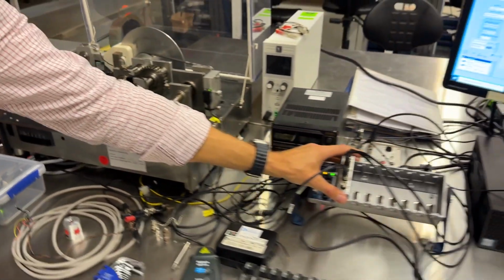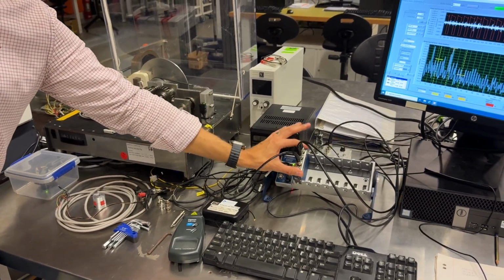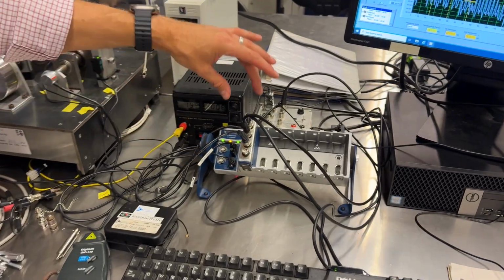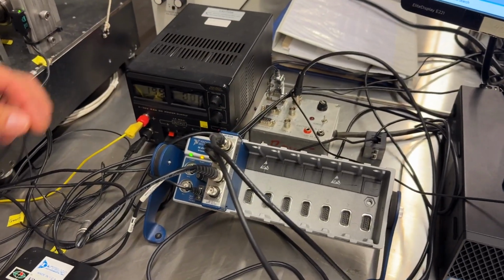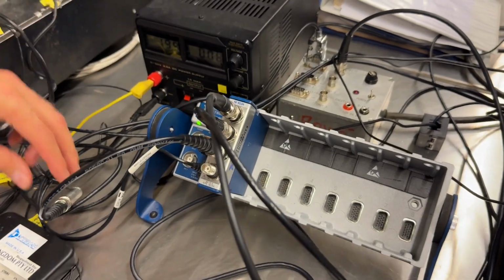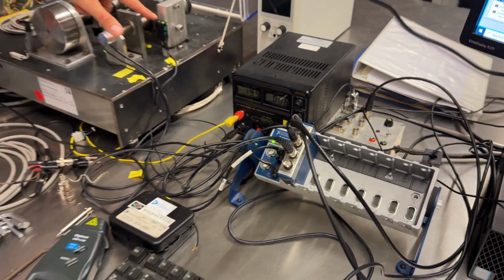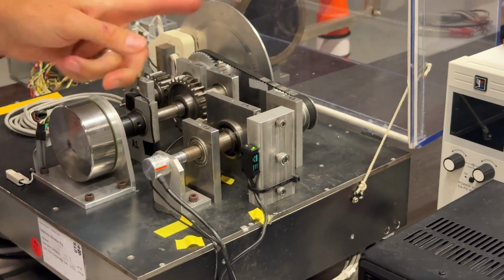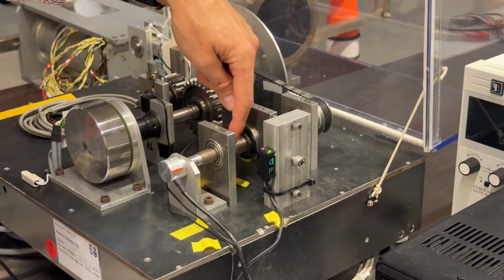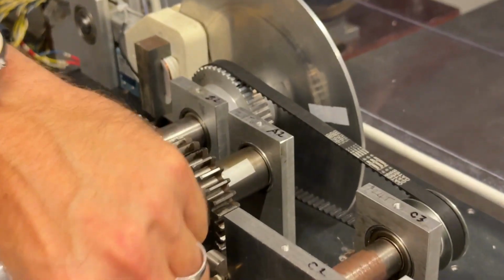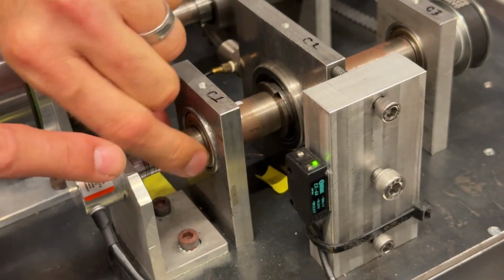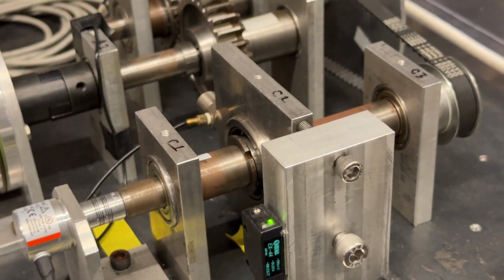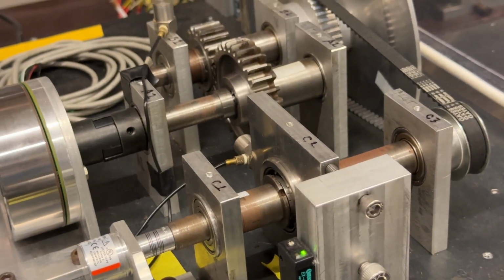We're using a National Instruments 9234 input module. It's a 4-channel voltage input module for our analog channels. It provides the IEPE signal conditioning. So we have, in addition, the tacho, which I've not actually mentioned yet. This is the tachometer here. This measures the once per rev speed of the shaft. There's a piece of tape on the shaft here, and as the shaft rotates, the tacho sees the tape and we get a red light, and it also provides an output to the acquisition system.